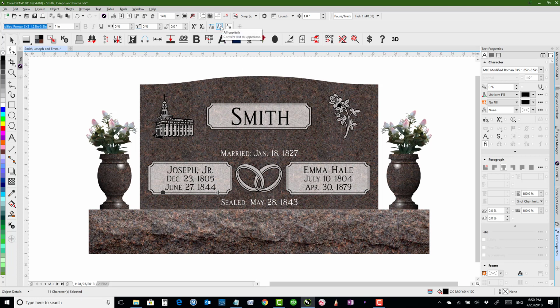So this AB button, if I actually hold Alt and click on it, so I'm clicking and dragging while holding Alt, that's dragging it then off of that toolbar. I don't want to drag it off, I want to make a copy, so I'm going to hold Control and Alt at the same time and just drag out here anywhere and let go of my mouse button, and that then creates a brand new toolbar for me with that tool.